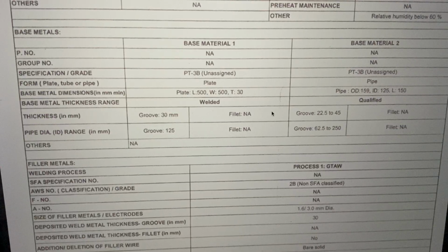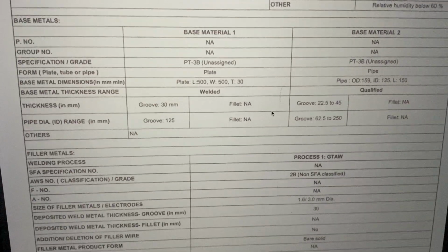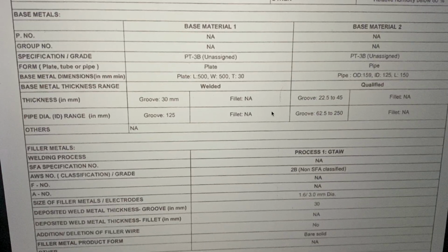either in this slot here, or we can put an annexure to our WPS and describe that form in a particular way, because some of the materials are very sensitive, from forging to plate to extrusion to casting, and the direction of the rolling, or the grain size, also sometimes becomes important for achieving the properties, and even, in certain cases, the defect, corrosion or metallurgical properties of the joint.